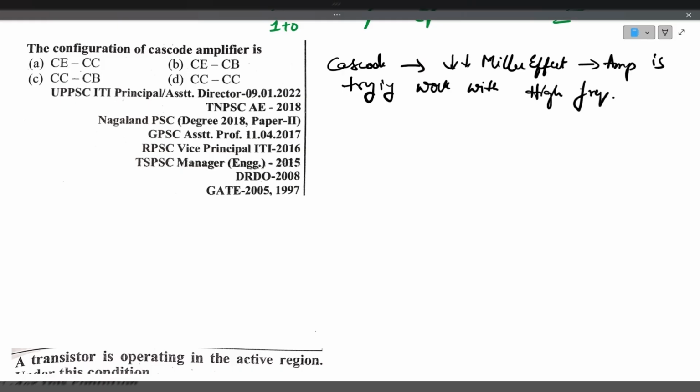Okay, that is the Miller effect. What is it? So this is the common emitter configuration. This is the base, this is the emitter, and this is the collector. There will be certain capacitances, which we call junction capacitances. This is the collector base junction, so there is a junction capacitance CBC. And here is one more junction capacitance, that is CBE. This is CBC and this is CBE.